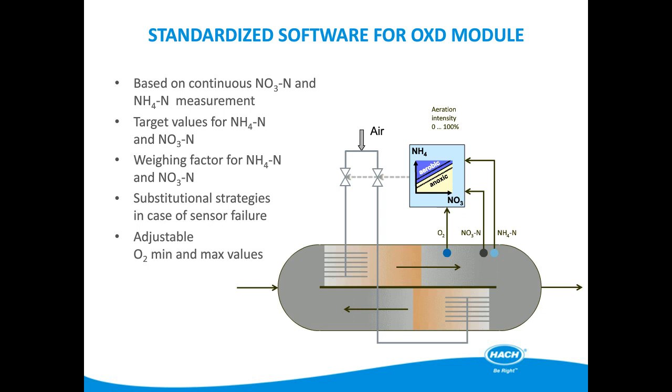If the measured ammonium concentration is over 3, but the total nitrogen is less than the consent, then the RTC will increase the aerobic volume of the ditch to nitrify the ammonium. As the ammonium concentration reduces to below the 3 milligram per litre threshold, the RTC will then reduce the aerated volume of the ditch by reducing the aeration intensity output and therefore increase the size of the anoxic zone in the ditch, thus reducing the nitrate content and keeping the site within its total nitrogen consent.